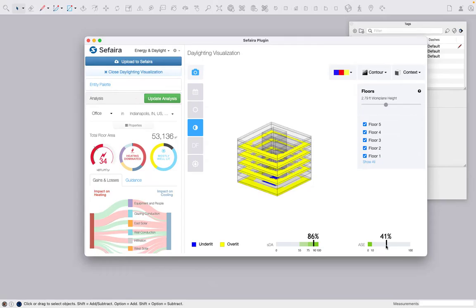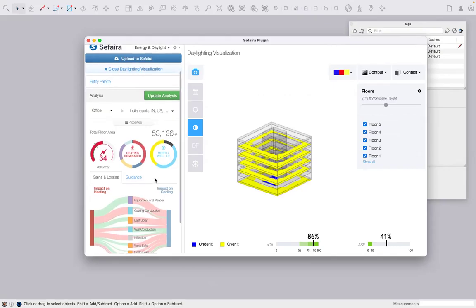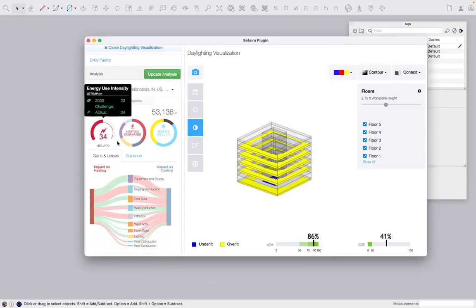And so there, you saw the ASE metric particularly shift. In terms of overall spatial daylight autonomy, it didn't change much, but the annual sunlight exposure did worsen when you lose the shading effect, and that's the result of more glare. You can see how much more is over in this corner of the building that was near that shading device. So this is where you can really start to investigate daylighting and energy, how much daylight autonomy you have versus glare, and really start to make a comprehensive concept design that's going to try to optimize energy and daylight.